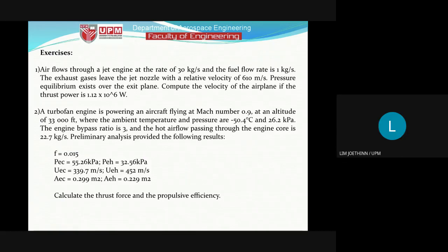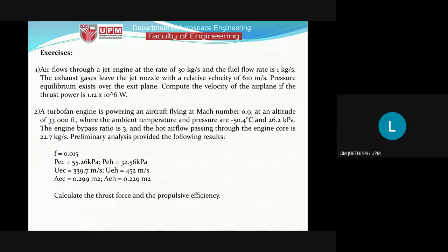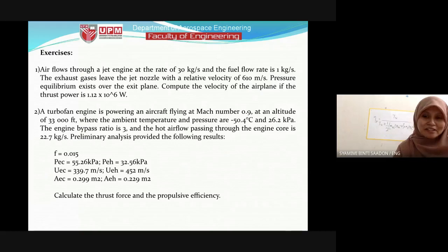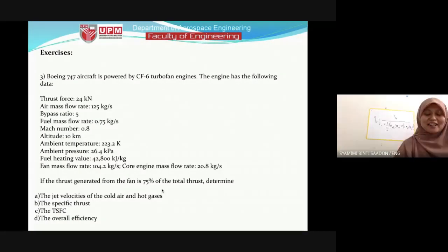Doctor, is the answer 0.9? Yes, 0.9, 90%. Around 90%, if you use the thrust of 19 kilonewton just now. So we get the answer around 90%: 90.32% or 0.9. Okay, we proceed. Everyone, try to finish your calculation later on. Okay, next. There is TSFC here.